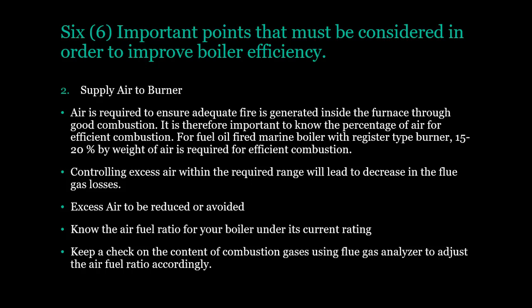Excess air is to be reduced or avoided. Know the air-fuel ratio for your boiler under its current rating. Keep a check on the content of combustion gases using a flue gas analyzer to adjust the air-fuel ratio accordingly.